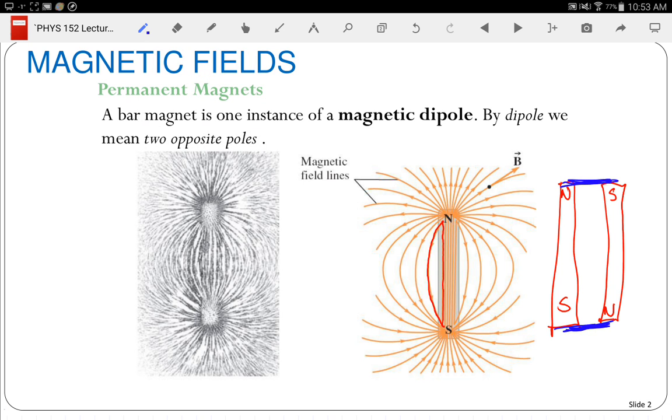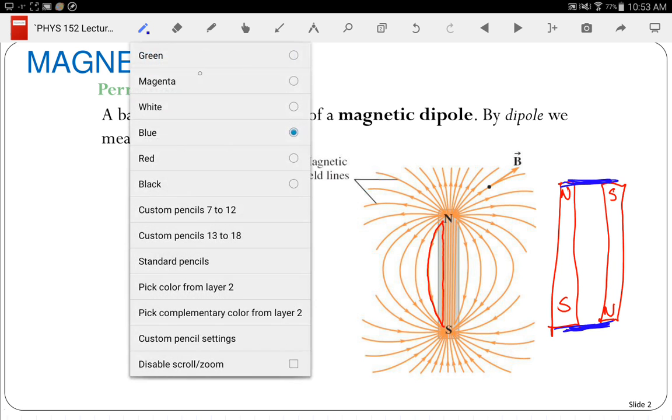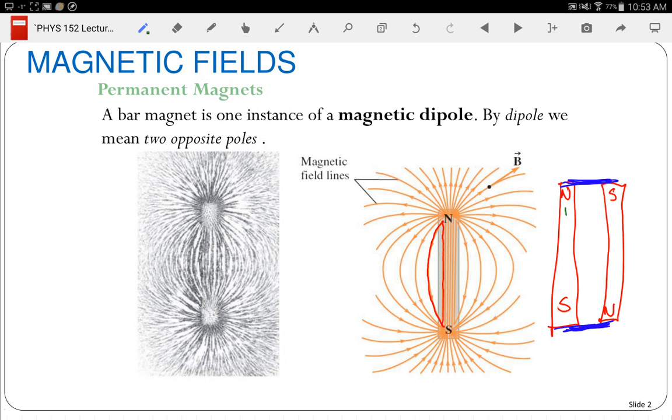What you're doing with those keepers is keeping the magnetic field concentrated. So with that arrangement, the magnetic field lines are just doing a loop like this and staying internal to your material. And that helps to keep the magnetism strong in the material. Now we're going to talk about what creates magnetism here in just a minute and how that helps to keep them strong. But that's why you should store them that way.